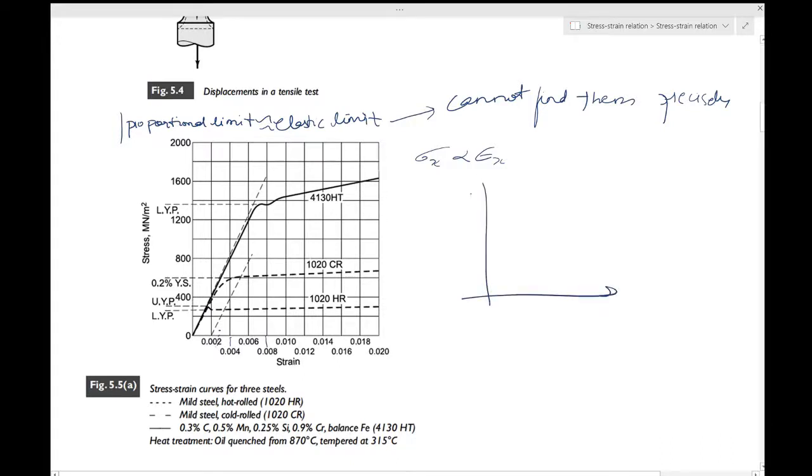and say for a very small strain, you get a graph like this. Just recall, how do you actually get this graph? What you do is you get certain data points, say over here, over here, over here, and then you draw this best fit curve, which is a line if the strain is very small, and then it can move along in a behavior like this. But the idea is that you have all these data points around you, and this is the best fit curve which you do to find this behavior.